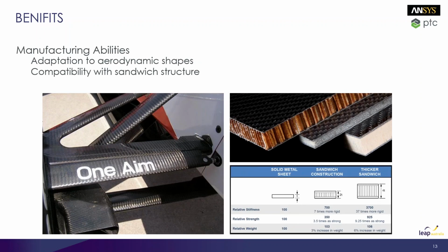I mentioned it earlier. One of the other benefits of composite materials is how we can manufacture our structures. So I mentioned because it's essentially flexible when we first start out with it, we can force it into some really interesting shapes using molds quite easily, and then we just set it hard. If we were to try and machine this out of metal, it's really not practical.